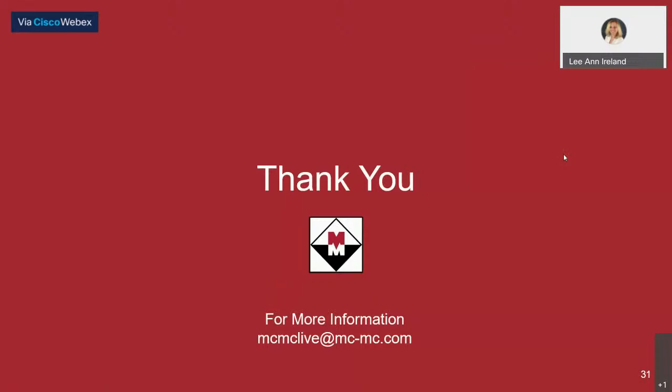We do have one other question for you, Doug, and it comes from Jack. He said, what happens if one person is writing the PLC program and one is doing the HMI program? How would you combine these together? Well, the only way you would be able to do that is if you have two licenses of Studio 5000. One person would be on their PC programming in Logix Designer, and one person would be on another PC with another license for the software programming the HMI.